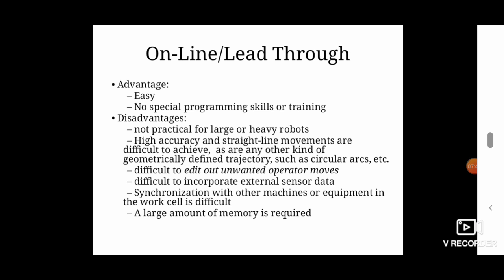But there are many disadvantages of online programming. First, it is not practical for large and heavy robots, because a large and heavy robot cannot be easily moved through the part. Second, high accuracy and straight line movements are difficult to achieve. Third, it is difficult to edit an unwanted operator move. It means if the robot is making an unwanted move,